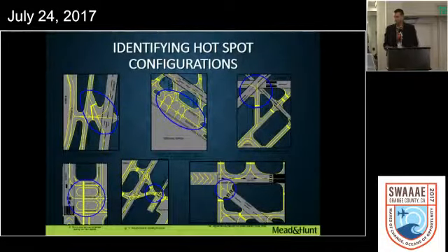So some examples of the hotspot configurations that they're noting. The first one is where you have the high-speed exit, so you have multiple taxi lanes, large, vast, open pieces of pavement. And the second one, they're trying to promote the addition of islands there again, so you don't have the large, expansive pieces of pavement.